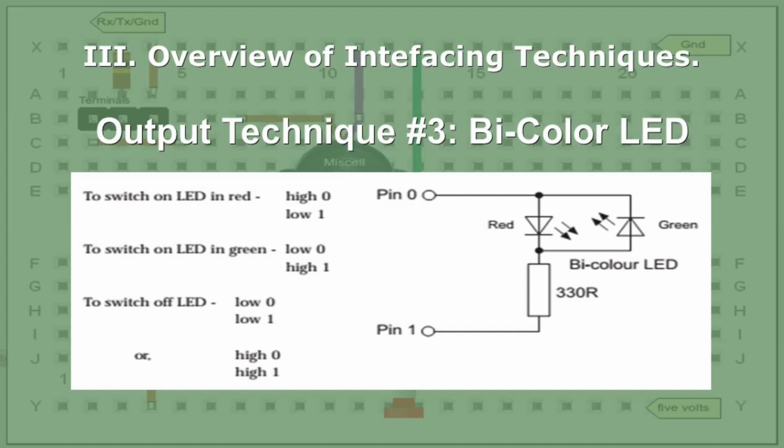Well, anyway, there's a bicolor LED. You could actually do a high on 0 to switch on the red LED. You could then do a high on one pin to switch on the green one. And to switch off the LED, you do low on 0 or low on 1. Depending on which way you do it will determine the polarity, because you can see the LEDs are biased the opposite way. So this is where you use a bicolor LED with a current resistor going to 2 pins. You turn whichever one you want high, whichever one you want low, to determine the current direction. And you can make it high or low that way.